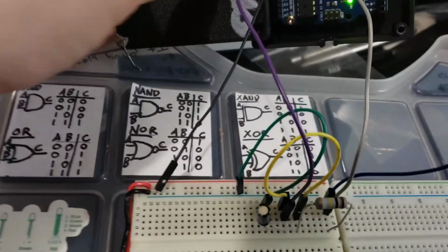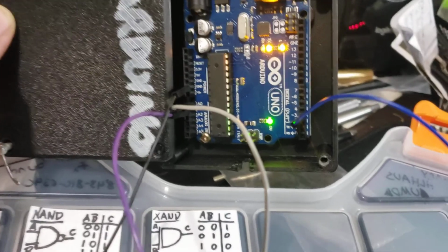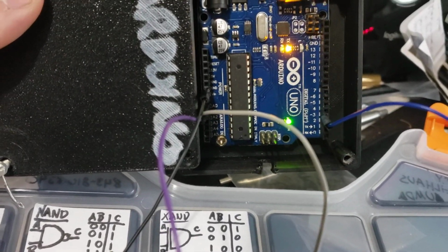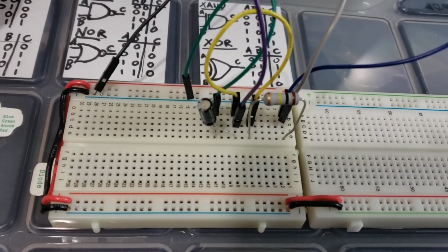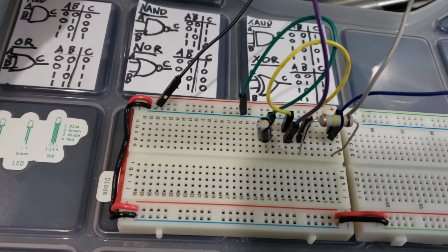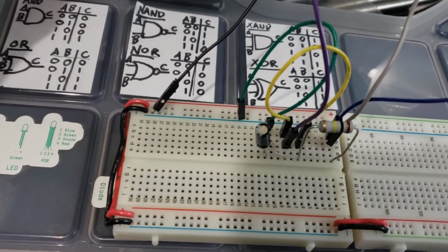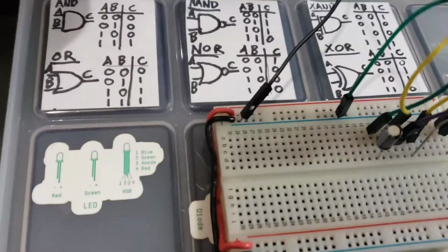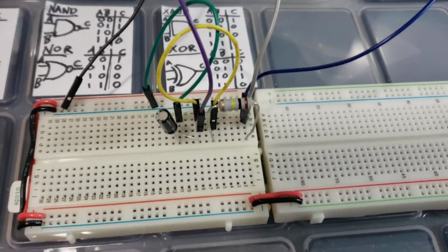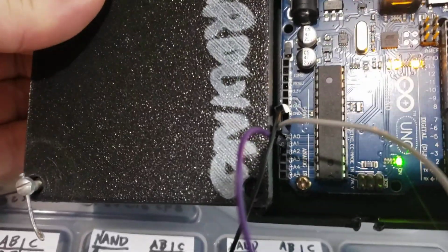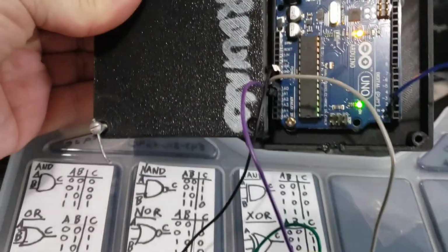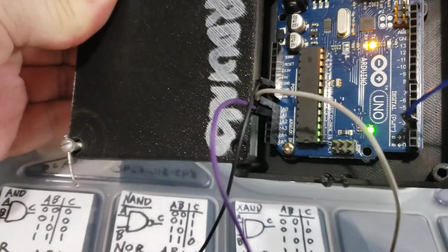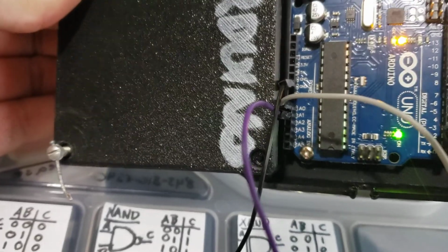Alright, so first off we have our RC circuit, starting with digital pin 3. That is our V in going through our resistor to the positive end of our capacitor, and then via green jumper to ground. The gray wire is our V in sensing at A0, and the purple is our capacitor voltage sensing at A1, both analog pins.